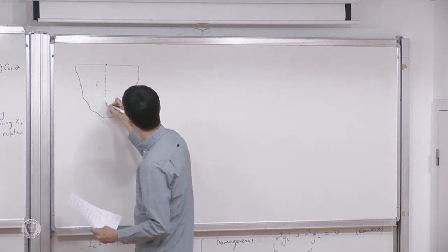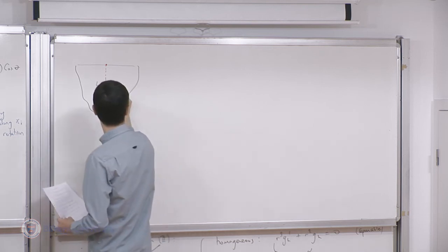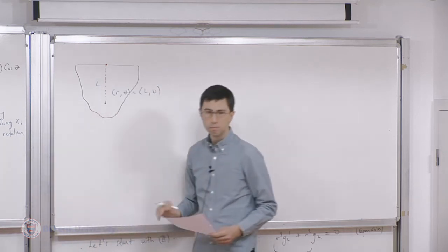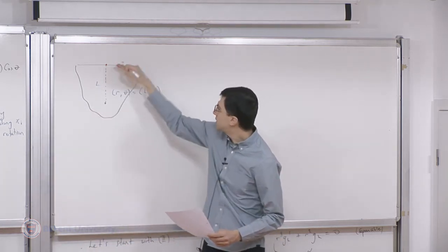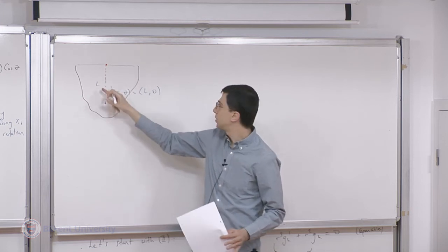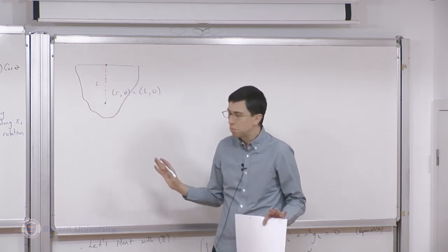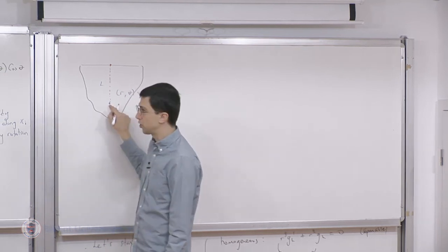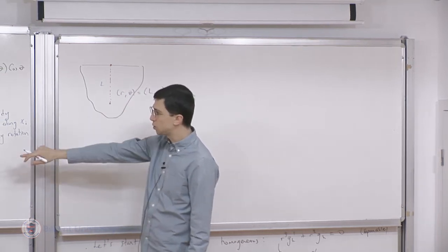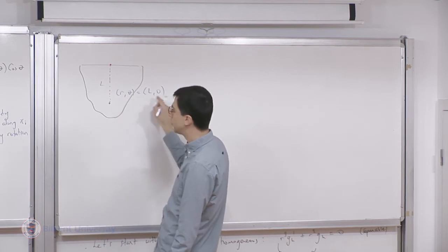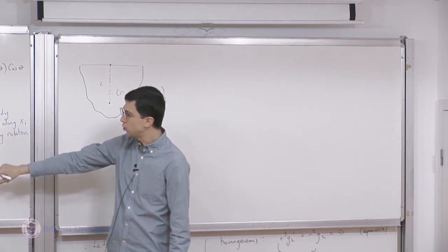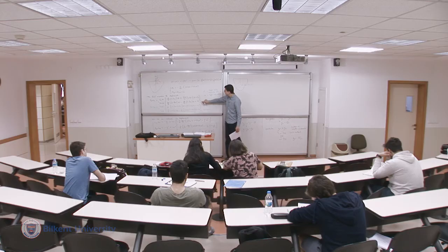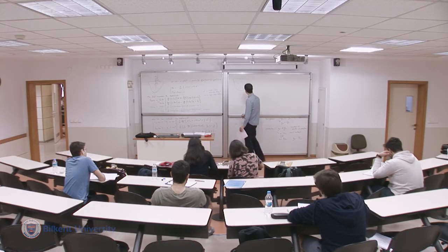So this is the point r theta equals L0. Okay? So I pick theta equals 0 almost arbitrarily, and I pick this length arbitrarily. And what I'm going to say is that this point doesn't move anywhere. So in other words, when I go to the displacement field and plug in r theta equals L0, ur and u theta must be equal to 0.